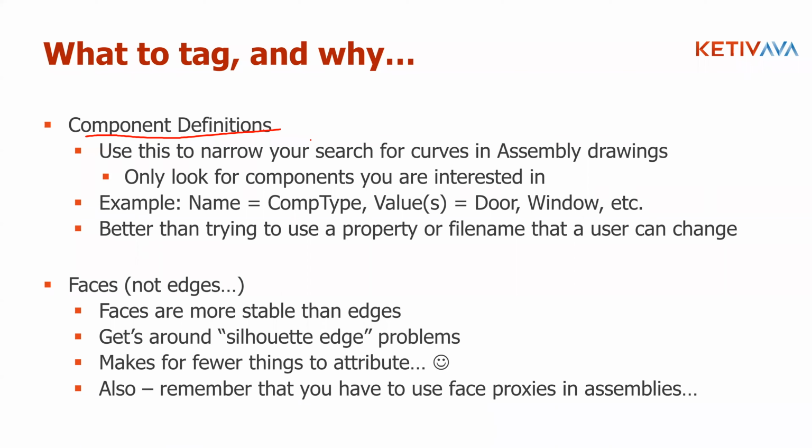If I've got a clean room design, or an air handling unit, or a mixing tank with a manway in it, we'll tag those things as you are this type, so that when we get to the point where we're putting a balloon on that for bill of materials purposes, or creating a specific type of dimension for that specific type of object, we're not sorting through all the other objects, having to say, what are you?